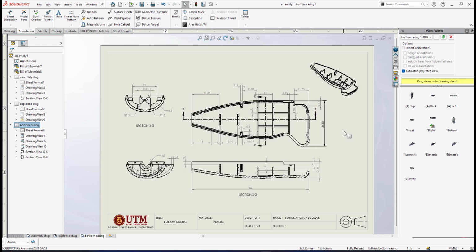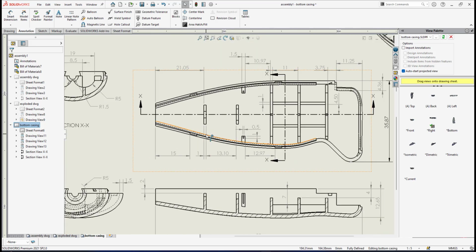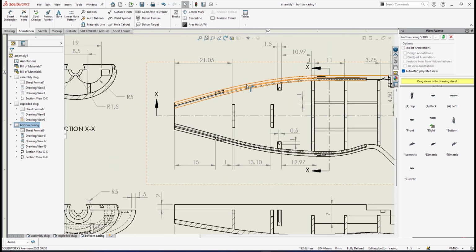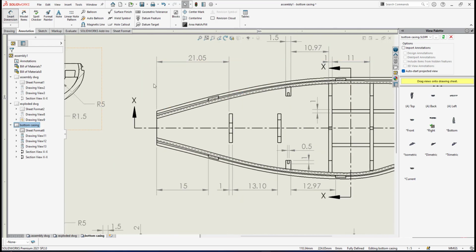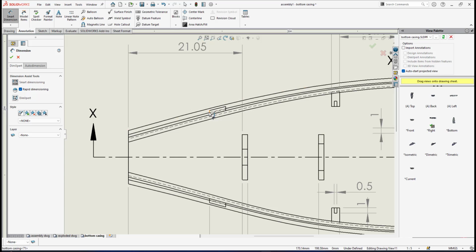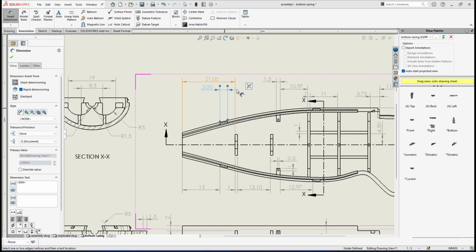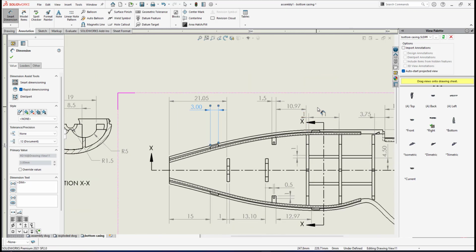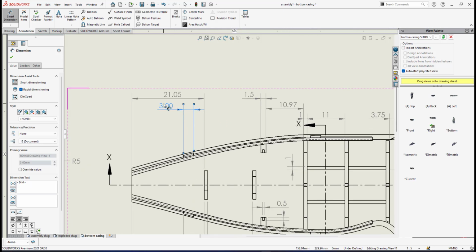Okay, the last thing is, I've given the position of this key here, right? I need to give the thickness of the key from here to here. I put it like this. It kind of pushes this 21.5 above, and here also. Since it is at the bottom level, let me bring it a little bit closer like this. And this one is maintained in line with the other one.